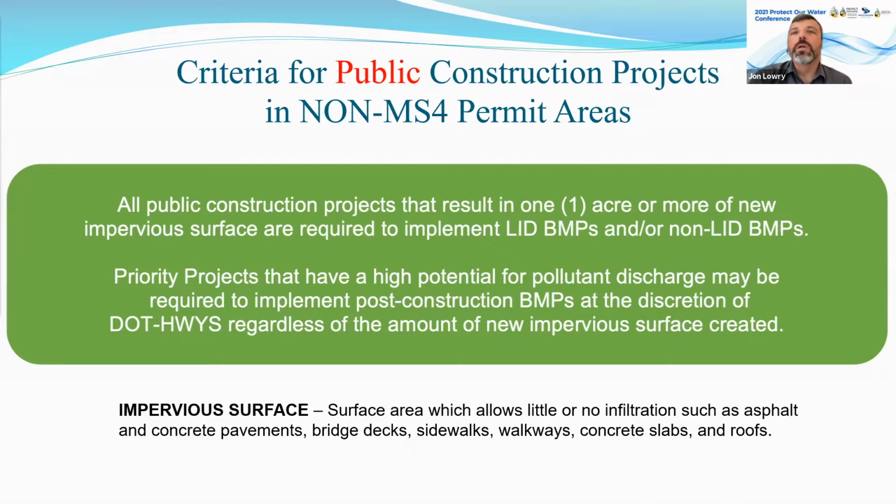So for those non-MS4 areas, it's just 1 acre of new impervious surface that triggers the implementation of LIDs or non-LID BMPs. And then again, it's always at the DOT reviewer's discretion, if the site has a high potential for pollutant discharge, that they can require them, even if it doesn't add a new acre of impervious. And so just, yeah, quick definition of impervious surface: surface area which allows little or no infiltration, such as asphalt and concrete pavements, bridge decks, sidewalks, walkways, concrete slabs, and roofs. Next slide, please.